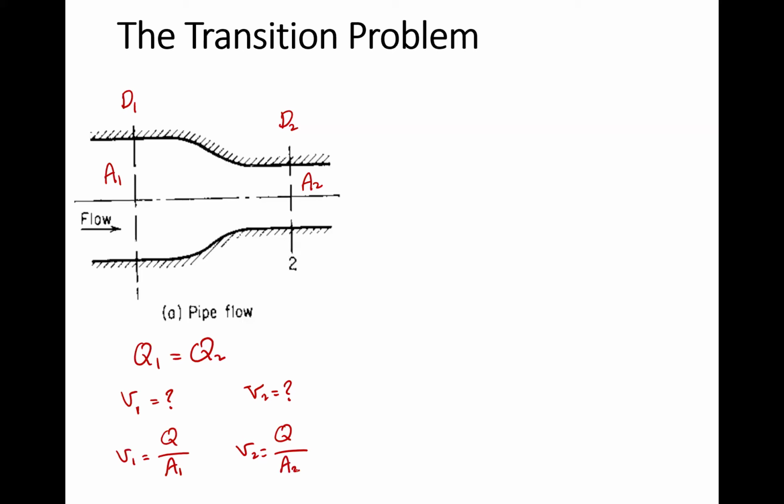What is happening here? Well, as we discussed before, in pipe flow, pressurized flow, one kind of simplification we get is that the geometry of the conduit is equal to the geometry or section or area of the flow, meaning that if the diameter goes down, if the area goes down in the pipe, the area of the flow will also go down in the pipe. That was something that we knew already, right? So why are we mentioning this? Now let's look at the similar case.